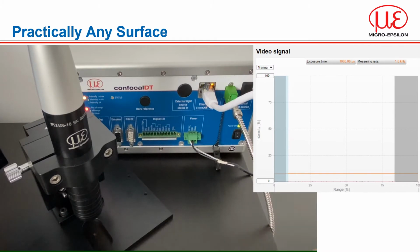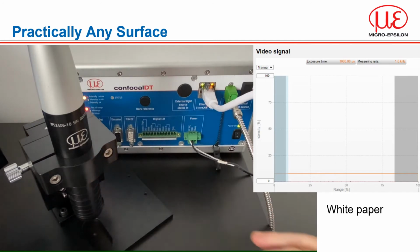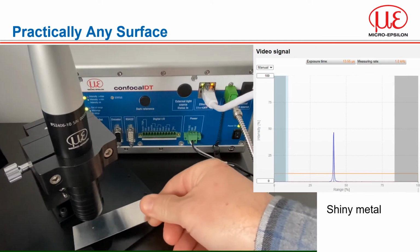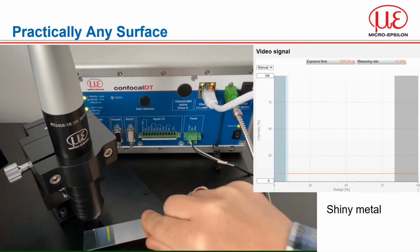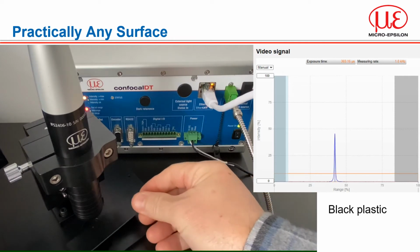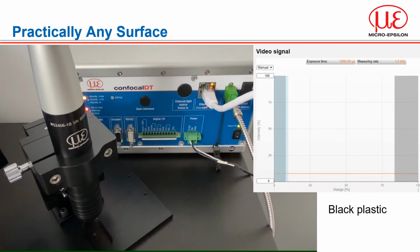By way of demonstration, I've set up the confocal system and, without any adjustments, placed a range of different targets in front of the sensor. The chart shows the video output signal. Transparent and perfectly mirrored targets are able to be measured also without any adjustment.